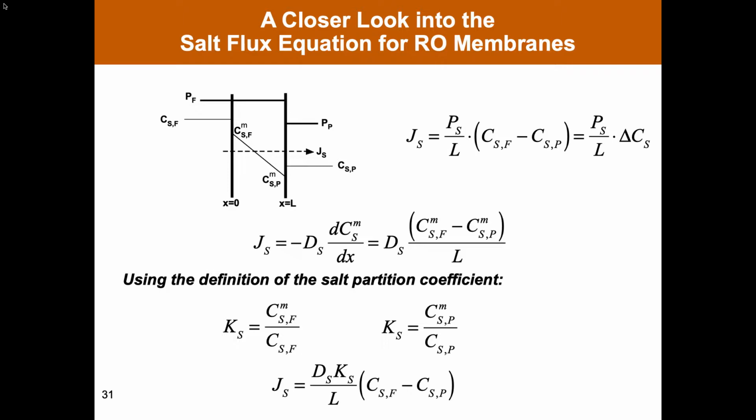And there may be a variety of thermodynamic models that can be used to relate the concentration of salt inside the membrane to that outside the membrane. Typically, over narrow ranges of salt concentration inside the membrane, we would assume that the partition coefficient for salt at the upstream face and at the downstream face of the membrane were the same. And with that assumption, we can replace the concentrations inside the membrane with those in the external solutions, which are the ones that you can measure physically in an experiment.